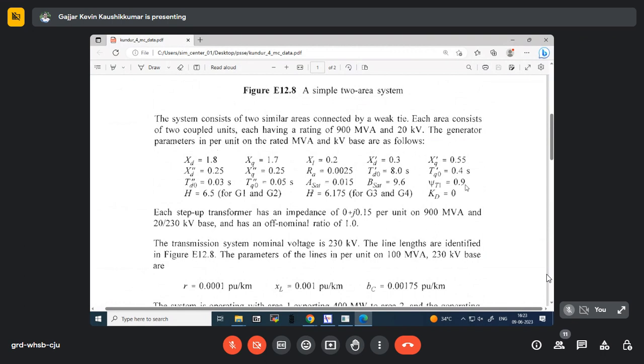I mean, the saturation occurs only after psi becomes more than 0.9. In per unit, psi and V we can assume to be equal. So this voltage also we can think of as 0.9 per unit open circuit voltage. So up to that the characteristic is linear, and then the saturation pops in.